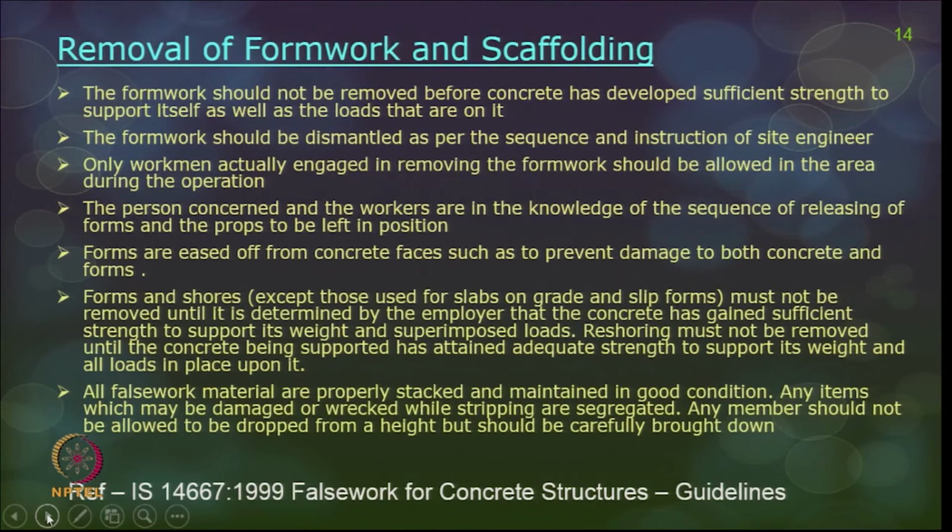So, when you are removing the formwork and the scaffold, there are some safety precautions you should keep in mind. The formwork should not be removed unless the concrete has attained sufficient strength. It need not be complete strength, but sufficient strength wherein the shores and reshores can help to balance the load. So, that should be kept in mind, and the load acting onto the structure also you have to keep in mind, whether that particular concrete has reached the strength, and then only should removal of the formwork be thought of.